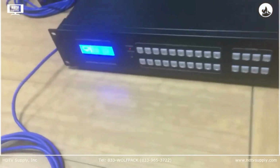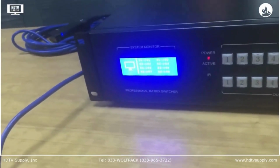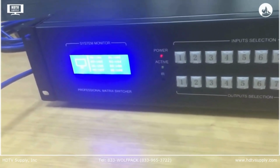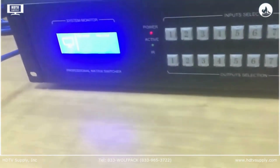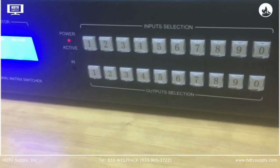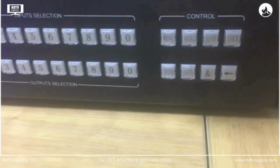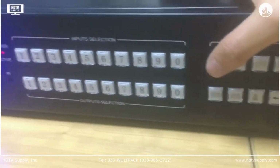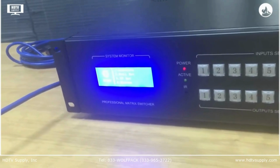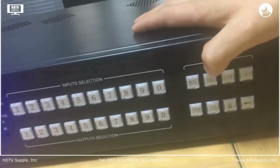This is the front panel of the modular matrix switcher. We have an LCD screen where we can see all the switching information, and also the IR, the power and the active indicator. The IR receiver is basically for the IR remote control, and we have the input selection buttons and the output selection buttons. For control, we have the menu button here, and once we press it, we can do the IP address setting, all the status checkout, or the bell setting. We also have recall or save for the presets.